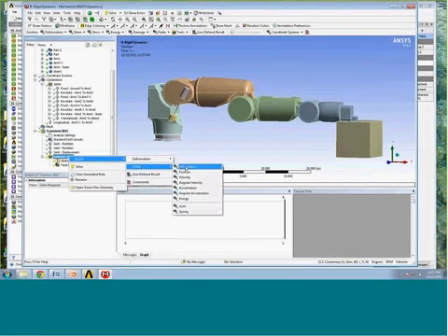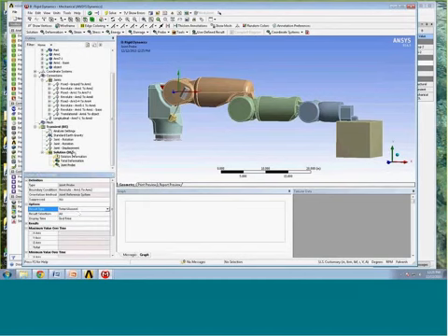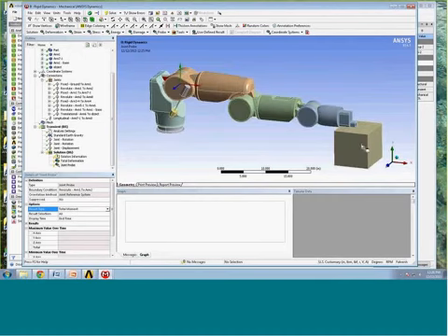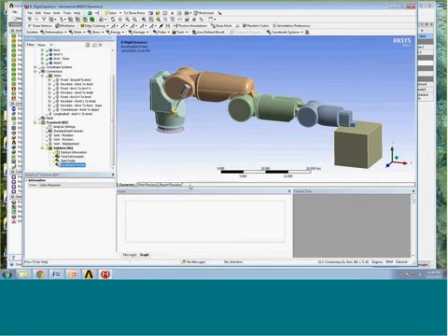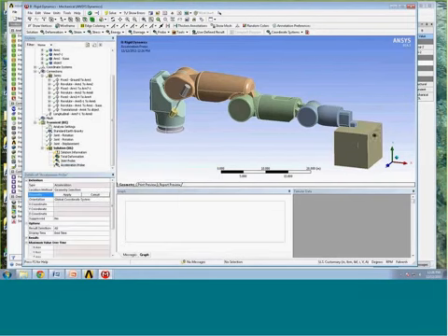That's the boundary condition, or the joint that I want to scope it to. And I want to look at the total moment in that joint. Other thing I want to look at is the maximum acceleration that occurs in the package itself. So if there's some sensitivity of the package to acceleration loads, that's something we can easily track. So I'll insert probe acceleration. I'm going to pick the package body, and then I can solve this.